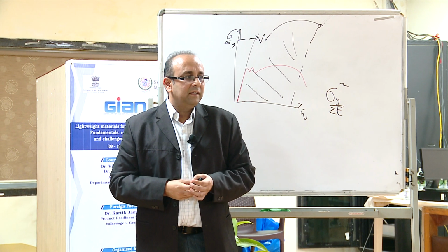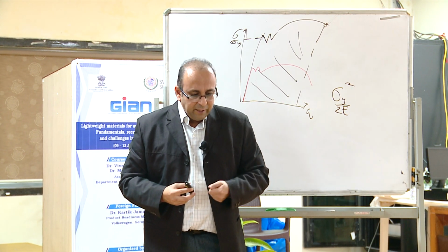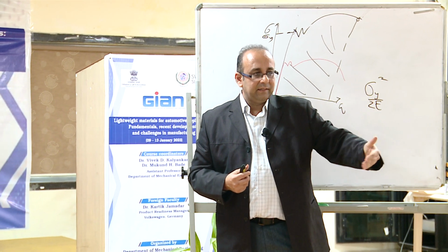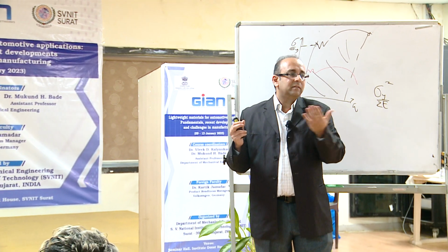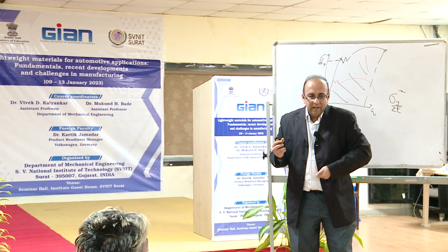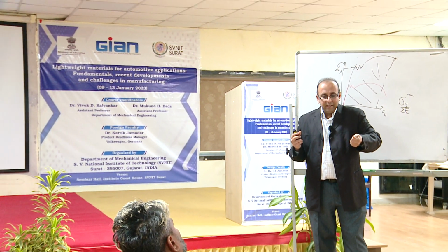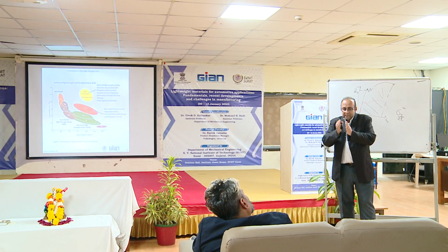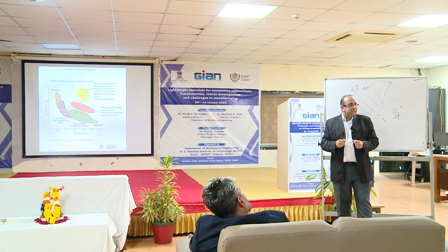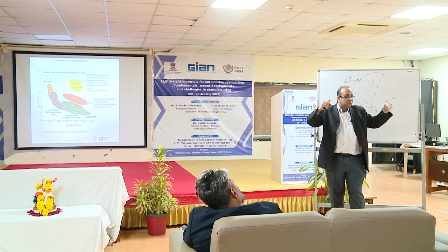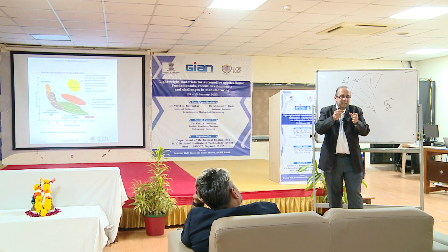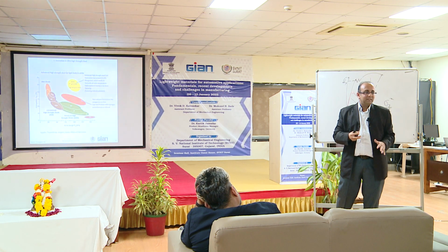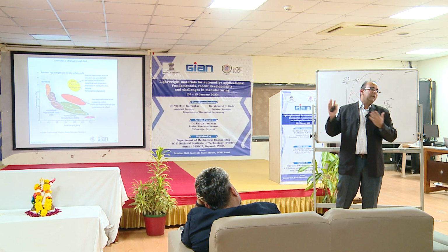The third problem is the welding of this part. When you do the welding of this part, basically you are creating martensite there, because actually this part has an austenite structure. Now welding it, you are basically cooling some area very fast, so you are creating some martensitic band. It means that basically you are creating a ductile structure in between brittle structure. Now there is a crash. What will happen? That brittle structure will collapse. So basically the weldability is a problem.